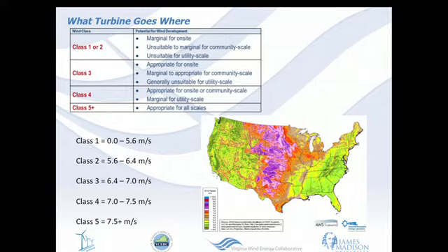Now this might be changing as technology increases. You've heard a lot of talk about increases in rotor diameters and blades, and turbines now starting to be able to function at lower wind speeds. This means that in the near future we might be seeing large wind farm developers looking in areas that have marginal winds, like a class 3 wind resource, because advances in the technology are allowing us to capture better energy from those wind speeds with larger rotor diameters. But that is on the verge, as still probably most of the development is going to be class 4 and up.